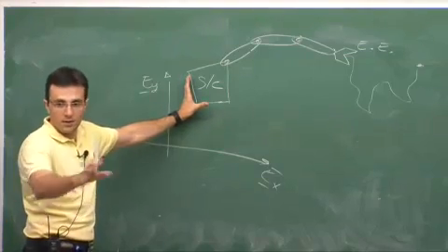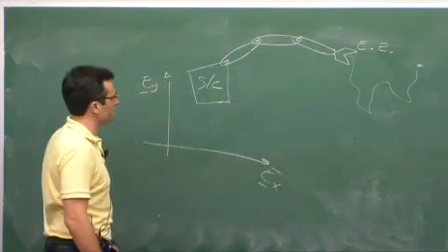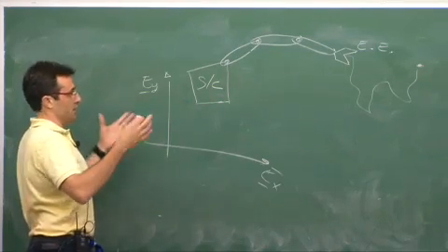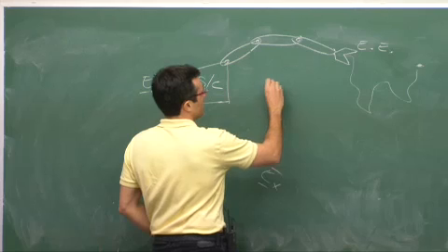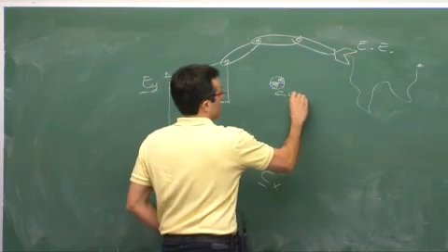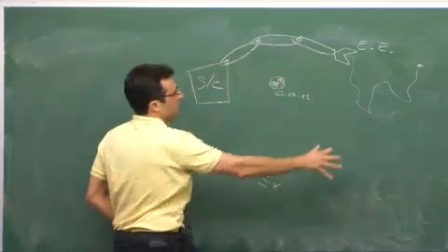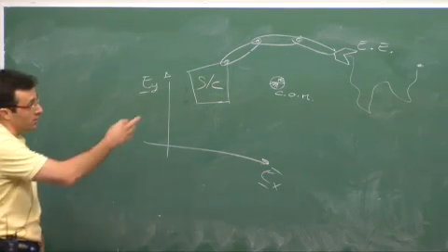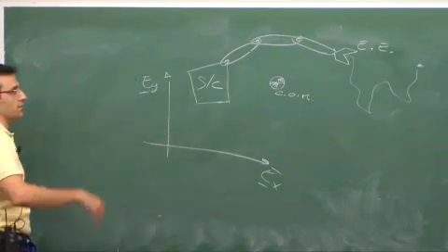You put it on the table, and a multi-link manipulator, you can control it. But the problem is that in deep space, everything is going to move. You don't have anything attached to the ground. So that approach starts from the assumption that if this system is not actuated, the center of mass doesn't go anywhere. If I look at this entire system from outside and there are no external forces or moments, especially forces, the center of mass will stay where it is in the inertial reference frame, or at most, it will move at a constant velocity.